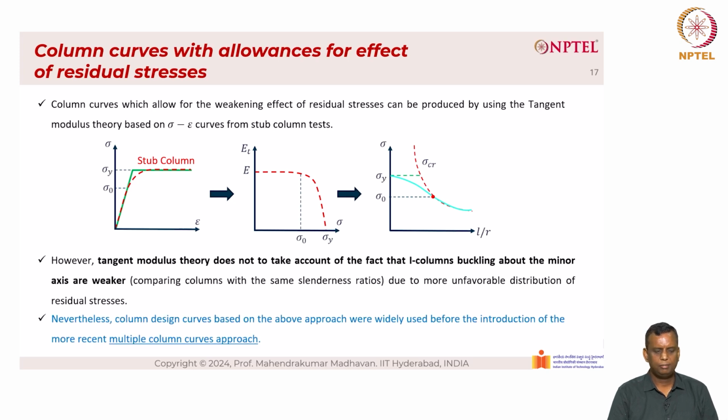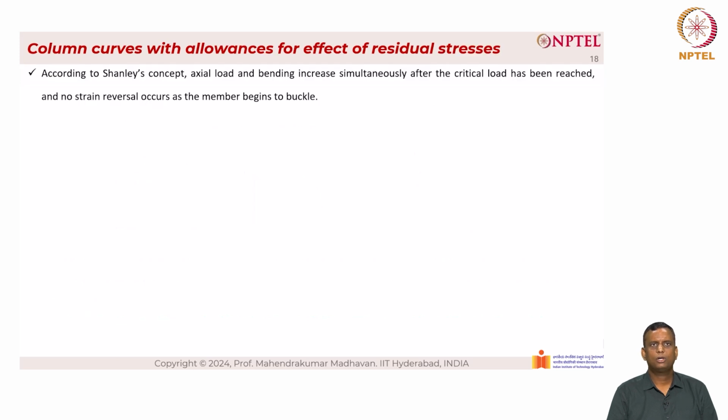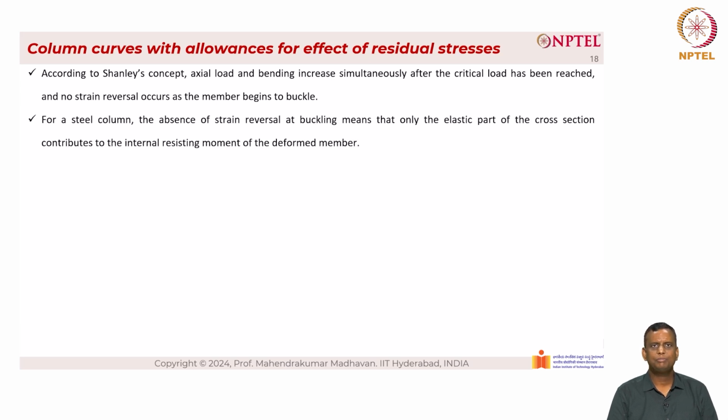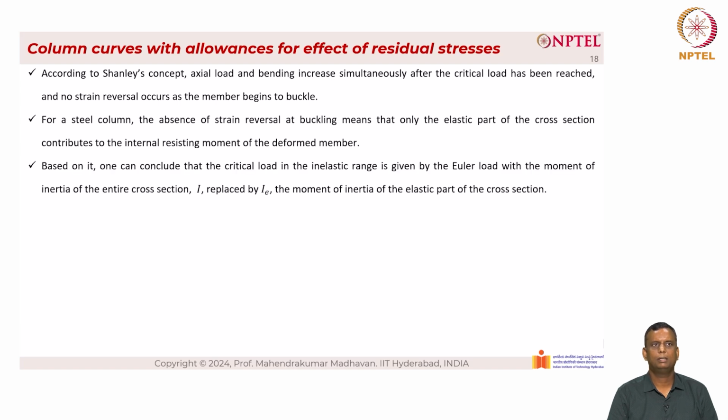Nevertheless, column design curves based on the above approach were widely used before the introduction of the more recent multiple column curves approach. According to Shanley's concept, axial load and bending stress increase simultaneously after the critical load has been reached, and no strain reversal occurs as the member begins to buckle. For a steel column, the absence of strain reversal at buckling means that only the elastic part of the cross-section contributes to the internal resisting moment of the deformed member.